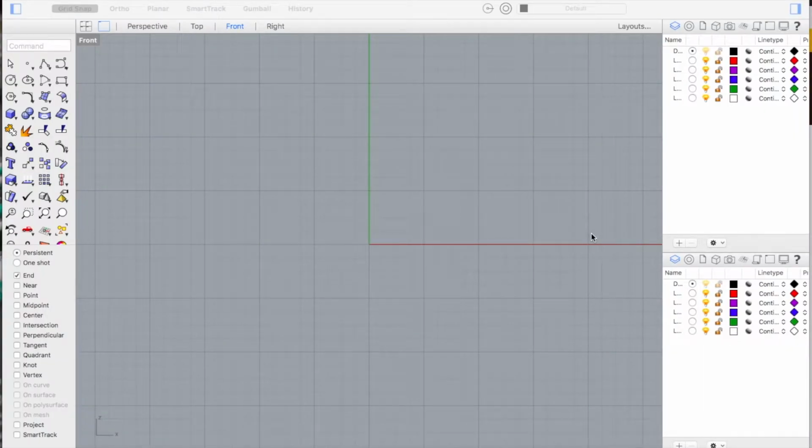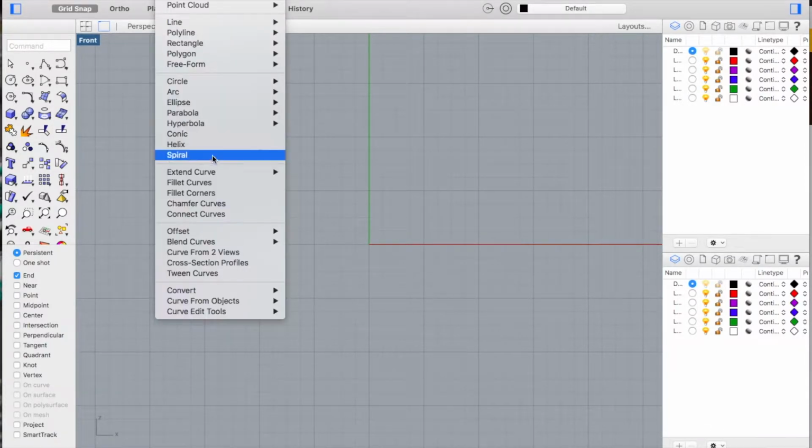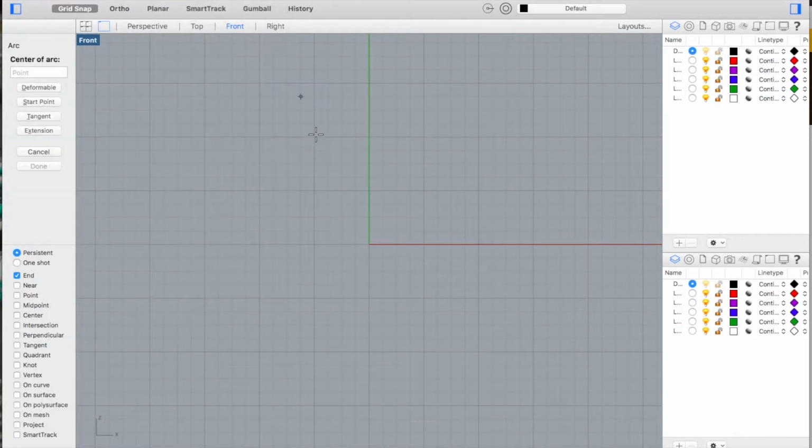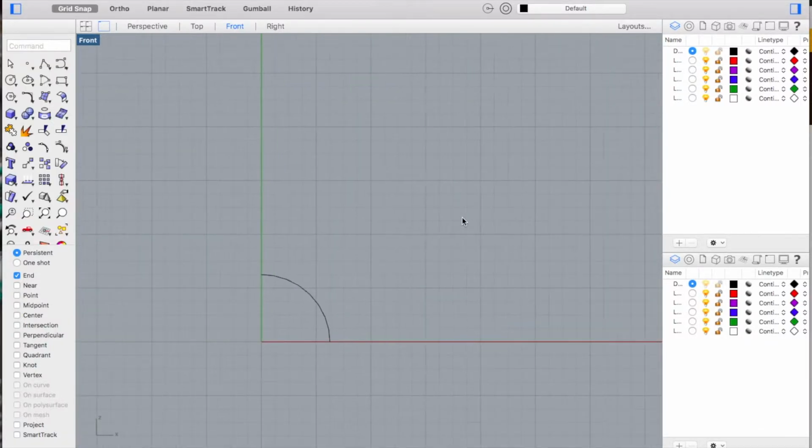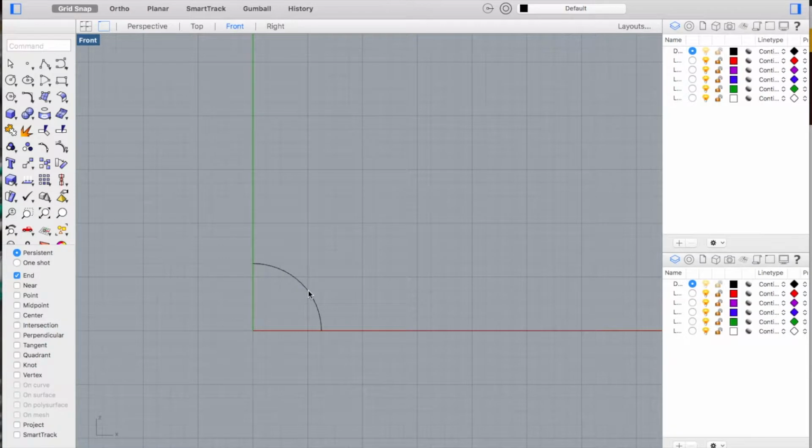The first thing we're going to do is use an arc. Our main arc or center arc starts right here at the origin point. So if we come up to Curve and go to our arc command, Center, Start, Angle, type in 0 for our origin, and then type in the radius of our arc. What I want to do is go straight up, so I'm going to hold down the magical shift key and go straight to the right. So that's our first line drawn, our center arc.